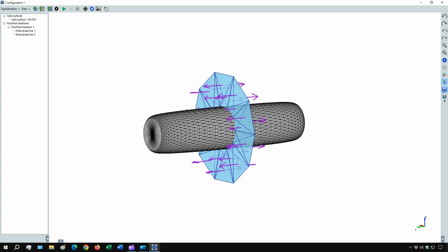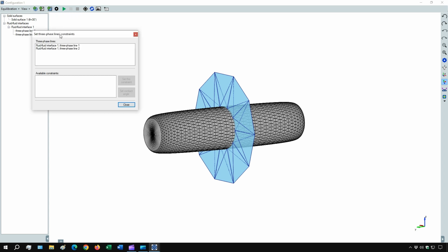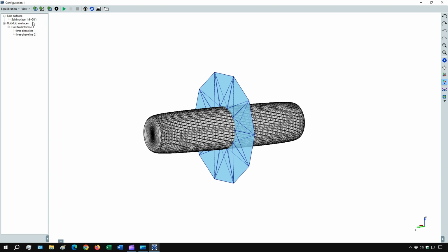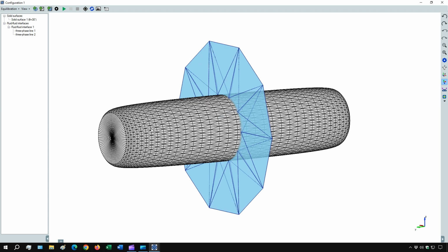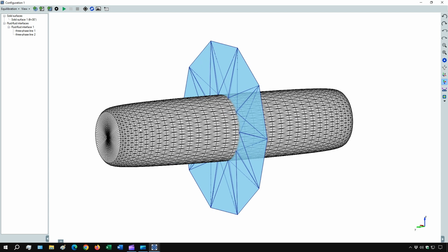So, this fluid interface mesh defines a droplet with an almost zero volume, and the topology of a torus wetting the cylinder. The two boundaries of this toroidal fluid interface mesh are constrained on the cylindrical solid surface. The selected Young's contact angle is 30 degrees. In the last part of this video, I will show you how I created this fluid interface mesh using Interface Equilibrator's built-in meshes.